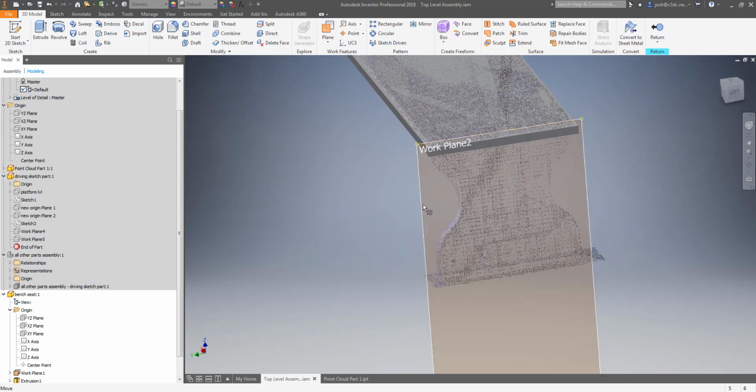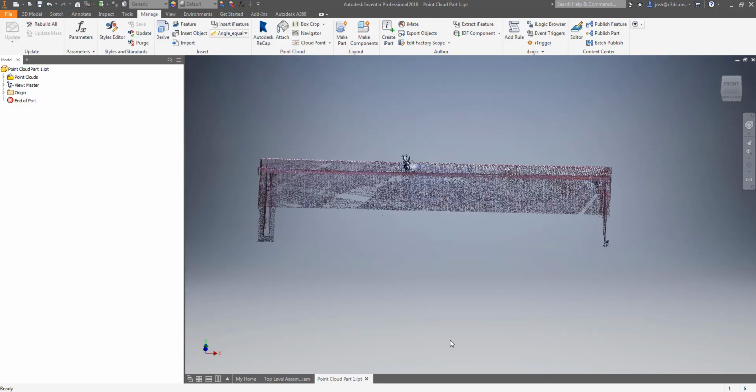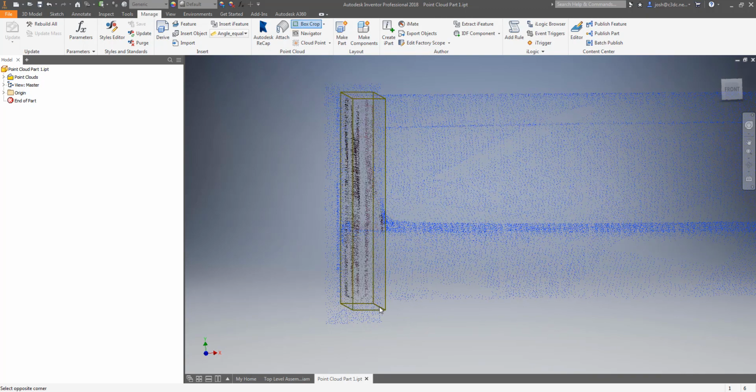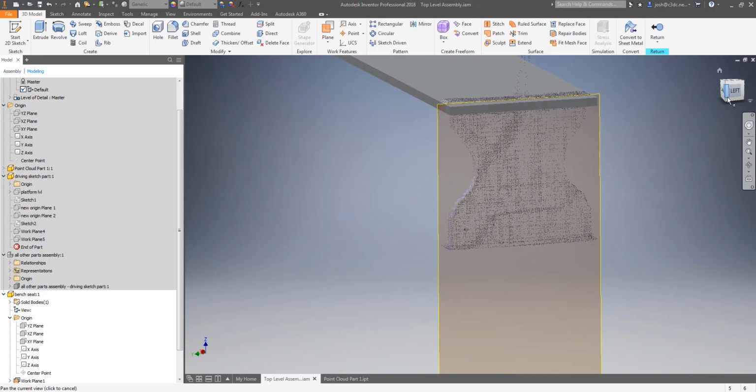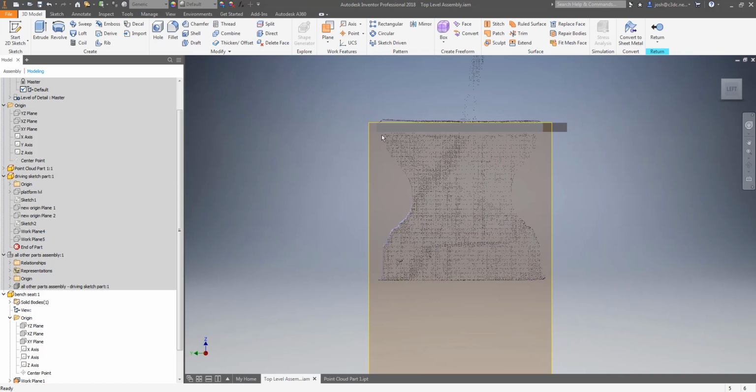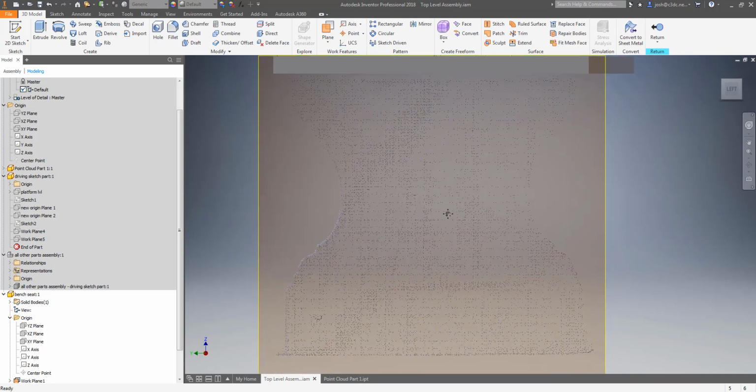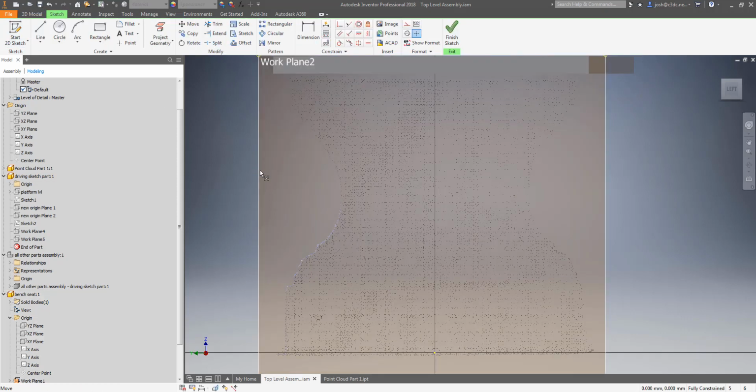The only difference from your normal workflow is that you don't have to think real hard about the dimensions, because you are using the point cloud as a guide for the sizes. There are other programs that will allow you to do this modelling process in a more automated fashion, where the program first calculates the profile of the point cloud and then, using an average of the points for that profile, creates a plane or a shape for the best fit.